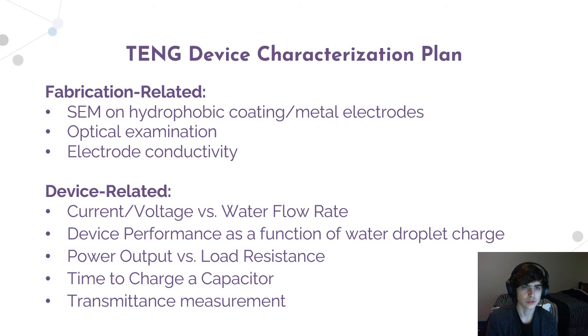To ensure that all desired electrical connections with the electrode layer in the device are made properly, probes in an SMU will be used to verify electrical connections. A 4-point probe measurement will also be conducted to measure the resistivity and conductivity of the electrode layer.